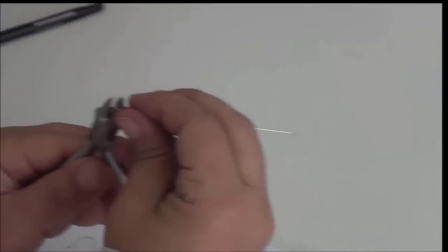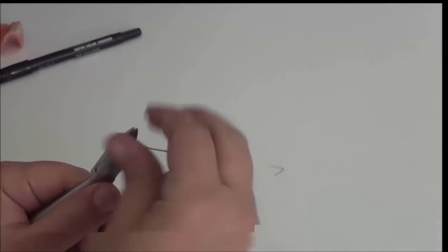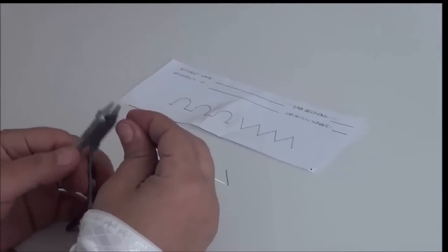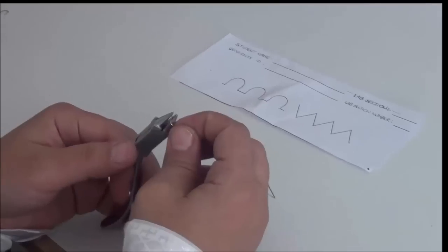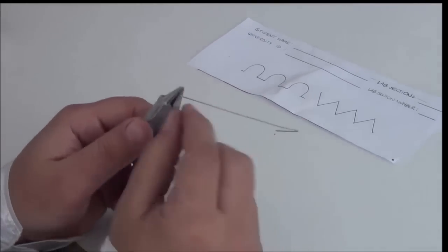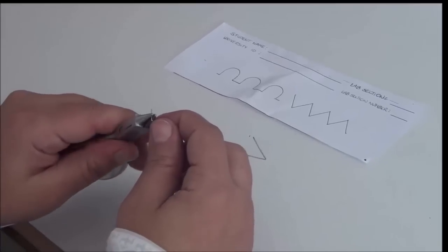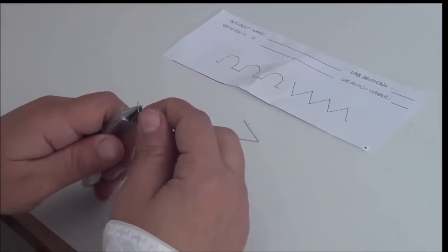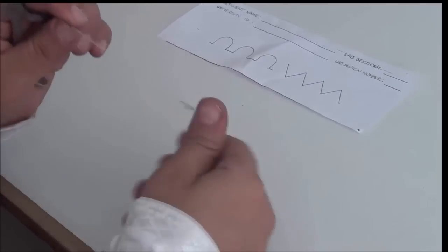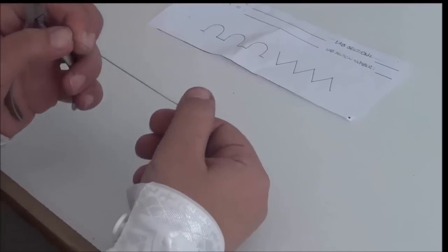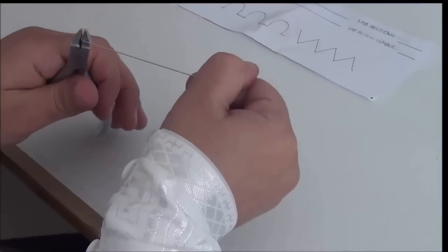After I bent the first 90 degrees, I move the angle away. I go around this part of the pliers and take the angle a bit away from the edge of the pliers. It's only 1 to 2 millimeters away, and I continue bending. So I'm trying to fix the direction. Notice how it rotates. This is the idea that I told you about. It keeps rotating, so sometimes you need to hold it from here to make sure that I'm oriented correctly.